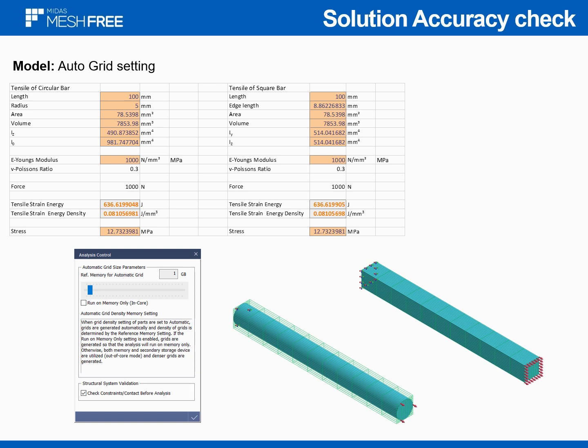So let's do some tests, and let's start from simple cases. I'm presenting now the data for the models I will use. I will use simple geometry. We will conduct a simulation of tensile elongation of a circular specimen. I will start my tests from the automatic approach, and I will use 1 gigabyte of memory to create an appropriate number of equations.